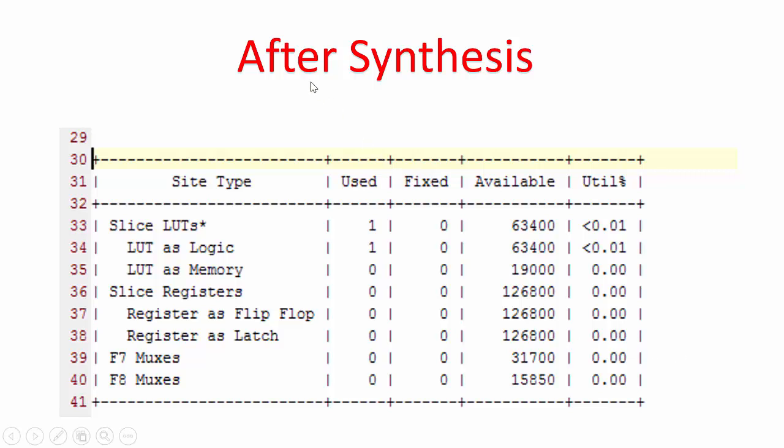After synthesis, you can see some results like this. How many lookup tables are utilized, how many registers are used, how many muxes are used. You can see in this report, and also how many are actually available on the FPGA, and what percentage you have utilized.